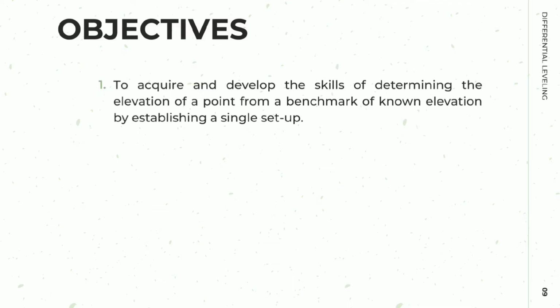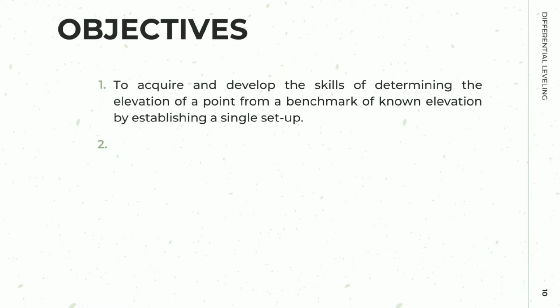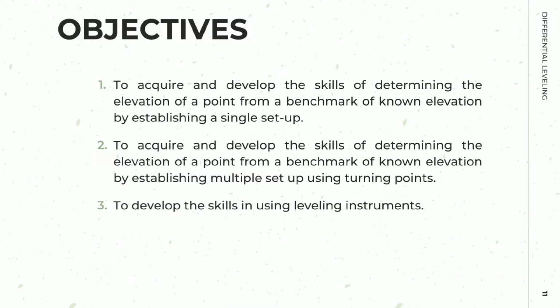The objectives of this fieldwork are: number 1, to acquire and develop the skills of determining the elevation of a point from a benchmark of known elevation by establishing a single setup. Number 2, to acquire and develop the skills of determining the elevation of a point from a benchmark of known elevation by establishing multiple setups using turning points. And lastly, number 3, to develop the skills in using leveling instruments.